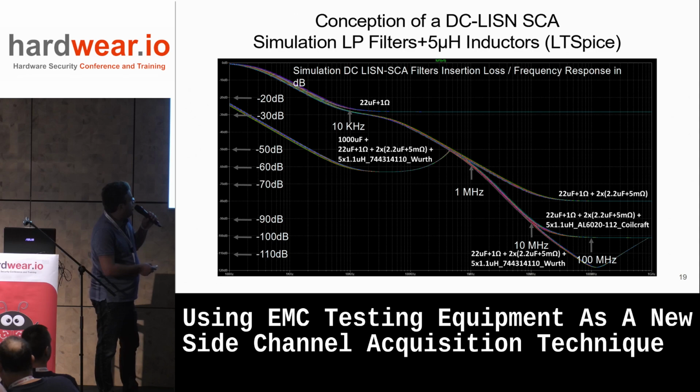And if we add also the inductor, we see also an effect on the filtering, which appears at about 1 megahertz, because the inductor also acts like a filter, and not only as an impedance adjustment to have 50 ohm. And then I have also added a very big capacitor, 1000 microfarad, and we see the effect even on the very low frequency.